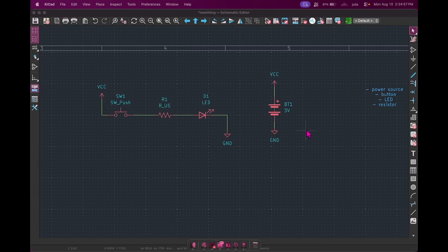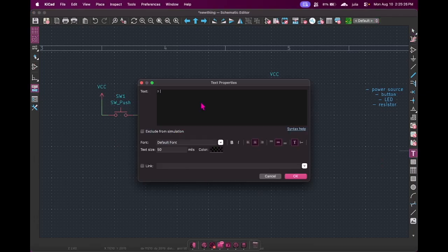Next, after you have your voltage figured out, you should figure out how much current you want going through. Honestly, just search up what components you have and what the normal amount of current is for it. I think 0.02 amps is the right amount of current for an LED. Then you can use Ohm's law to calculate how much the resistor would need to be, so that's 3 equals 0.02 times your resistor value.